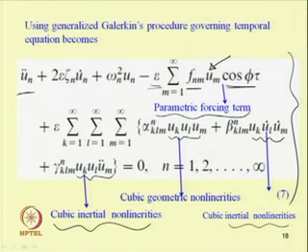Now, this equation is written in terms of the nth mode, and one can note that this forcing function, with m equal to 1 to infinity, contains the interaction of the other modal frequencies, the other modes also. Instead of taking n, one can have this interaction of the other modes. This term can be taken from the u_m term, so it can be u_1, u_2, u_3. That means the nth mode is influenced by the presence of the other modes in the system.